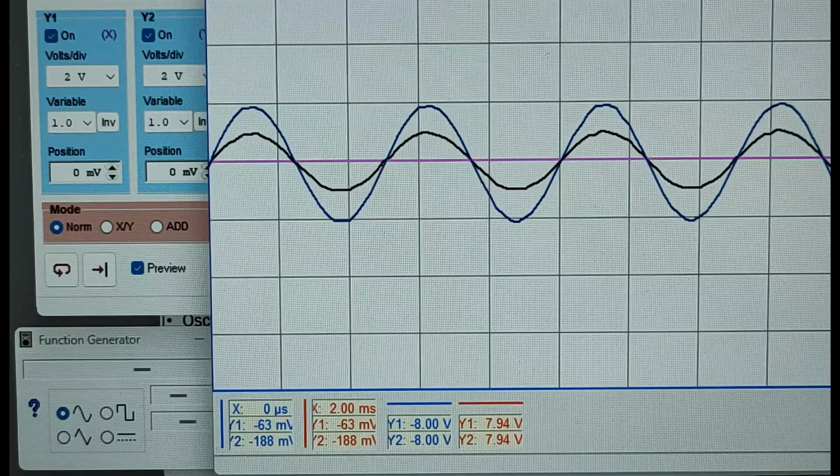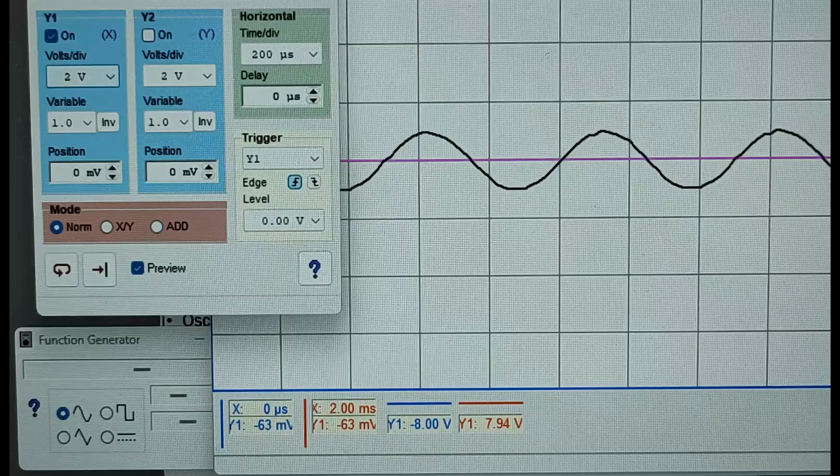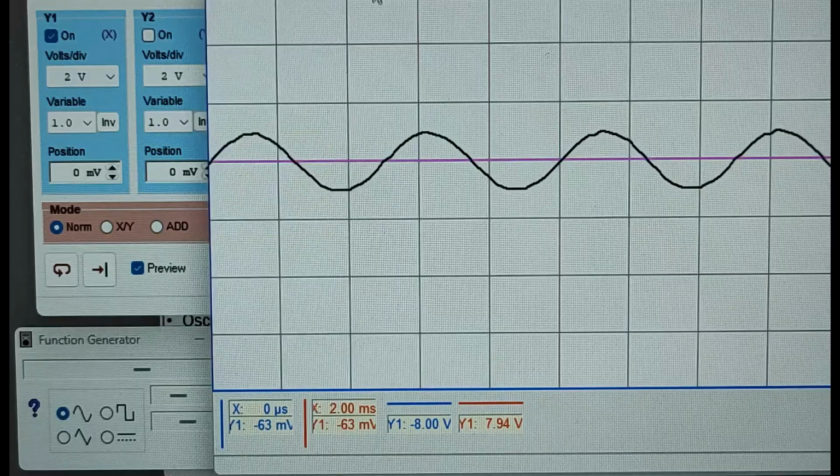And I mentioned earlier that our waveform should have more or less the same amplification, which means the input waveform would be amplified by that much, based on the computation of the amplification factor. If our amplification factor is 2, theoretically, then I should also have 2 here. How do we verify that? Let's check the peak-to-peak voltages of both. I'll start with the input waveform.